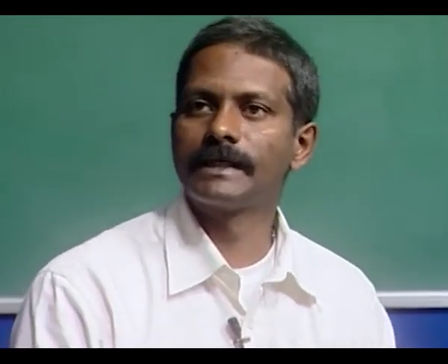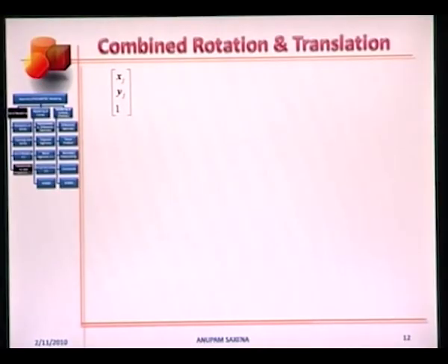Combined rotation and translation. But first, a little bit about the additional entry that I had introduced in the position vectors earlier. This column vector with entries xj, yj, and 1 is now termed the homogeneous coordinates of Pj. xj, yj would have been the natural coordinates. You would see these coordinates coming in a lot of use in areas like robotics and vision.